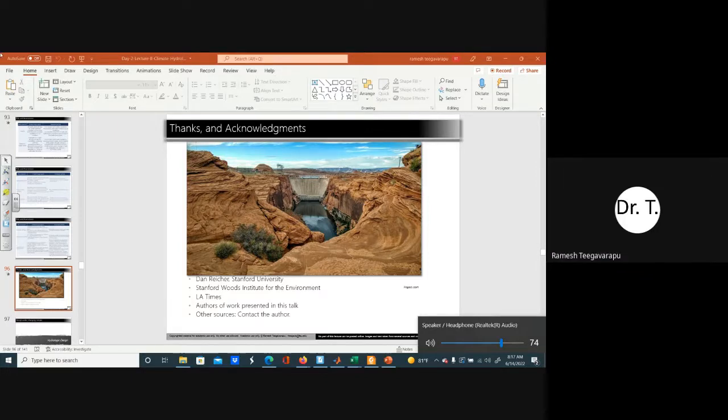The main issue that we have seen in many failures within the United States or problematic flooding issues is the lack of forecast of two things. One is the watershed conditions 10 days or 15 days before the actual event, and the precipitation forecast. So if the precipitation forecast is available, for example, if atmospheric rivers are coming your way, which are going to dump a tremendous amount of rainfall, then you have a reason to believe that you have to operate your dam in such a way that you provide enough extra storage. So the reliability of the forecast and the reliability of the soil moisture conditions will really help determine how much water will come into your dam.